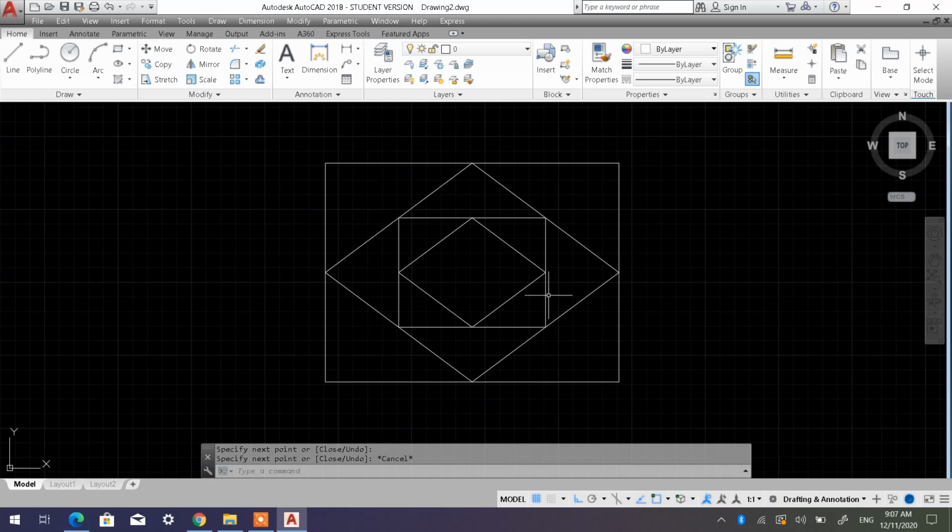So if we already know the midpoint, we don't need to key in the measurement value. Like at the start, we had to enter 200 mm, then bring our cursor up 150, then left 200, then close it. For the first one we have to do that. After that, since we have chosen the midpoint, we don't need to enter the dimension. We just play around with the symbol, okay, got it.